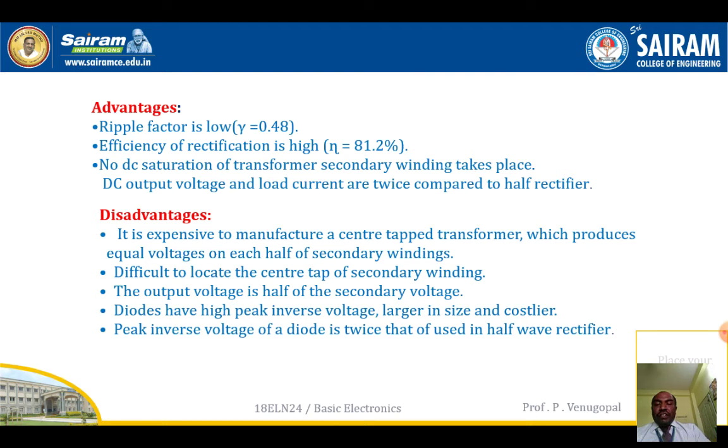Next advantage of the full wave rectifier is that no DC saturation of the transformer secondary winding takes place, and DC output voltage and load current are twice compared to the half wave rectifier.